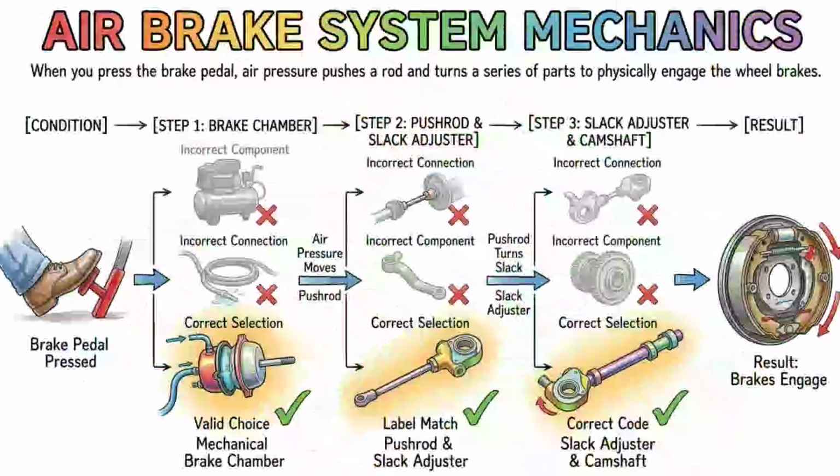To understand air brakes for your exam, you must first realize that a modern commercial vehicle actually uses 3 different braking systems combined into one. These 3 interconnected systems are the service brake system, the parking brake system, and the emergency brake system. The service brake system applies and releases the brakes when you use the brake pedal during normal driving. The parking brake applies and releases the parking brakes when you use the yellow or red parking brake control knobs on your dashboard. Finally, the emergency brake system uses parts of both systems to stop the vehicle in the event of a brake system failure.